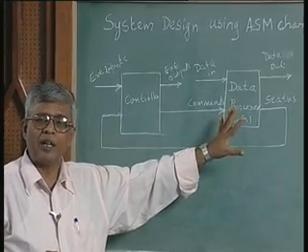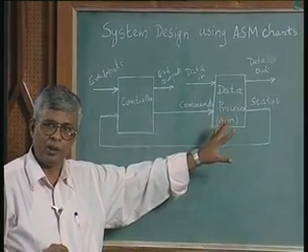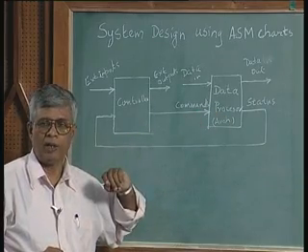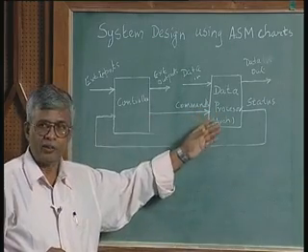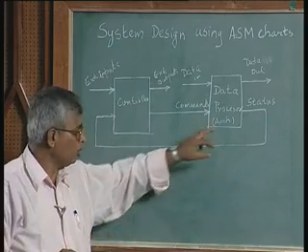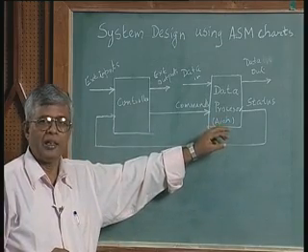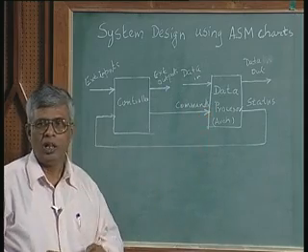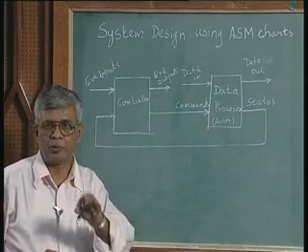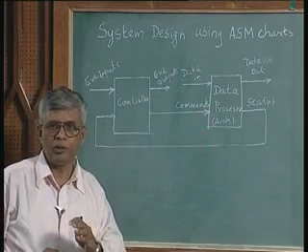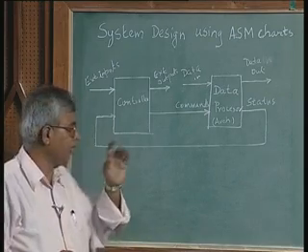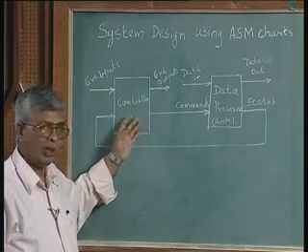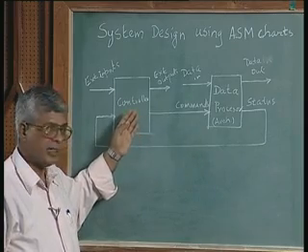are usually elements which are available, functional blocks which are available. A multiplier can be bought, registers are available off the shelf, it can be an adder which can be purchased. So, most of the time the architecture functional blocks are available off the shelf. Sometimes you may not have the exact specification, but you may have to work with that. On the other hand, the controller is what you design, this is specific to the problem you are designing, specific to the design. It is designed by the designer.